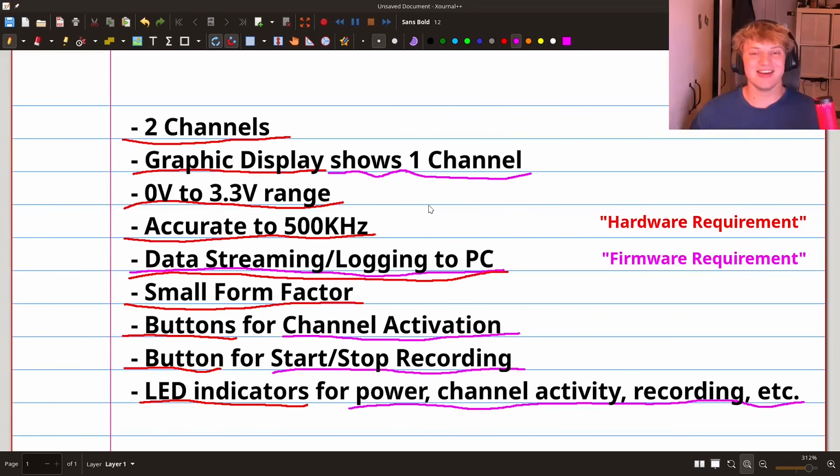And it certainly can't take negative voltage without assistance. So what we have to do is limit our input range to 0 to 3.3 volts for now. We could add an analog stage with op amps if we want to shift negative voltages up or scale large voltages down. But this is a thing for a future iteration of the design, and this is what I'm talking about, right? For now, we're keeping things simple and accepting only this 0 to 3.3 volt range.